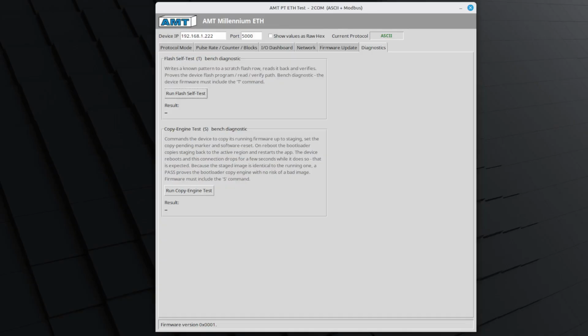The second jumper is factory reset. Factory reset restores the module to its factory IP address and default 4-digit code. While the factory reset is active, the module is in a holding state with a flashing onboard LED. The pulse total and calibration factor remain untouched.